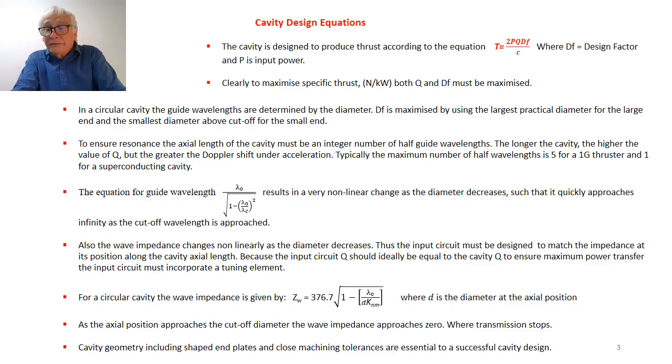And in the real world of microwave engineering, cutoff exists, and therefore a good check on your design process, whatever you use, and we'll come to the process that I've used in the next slide, but however you do it, what you should do is to take the small diameter of your cavity below the cutoff diameter and see what your software tells you is going to happen. If it doesn't tell you that the whole thing collapses, then you've got your design process wrong.